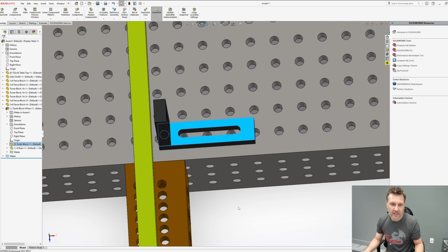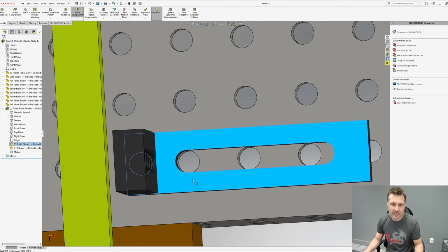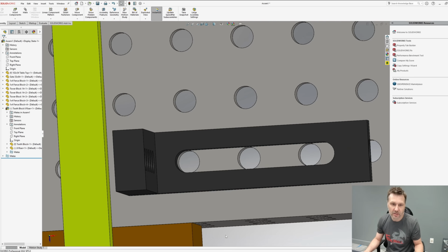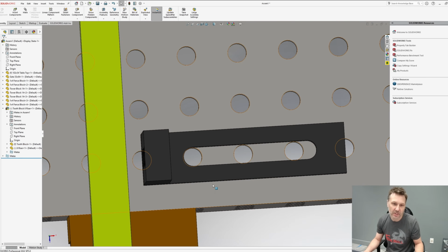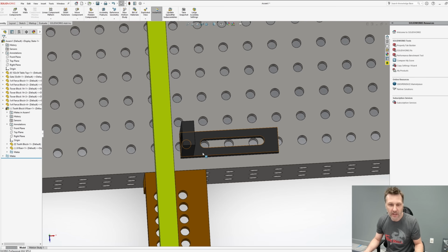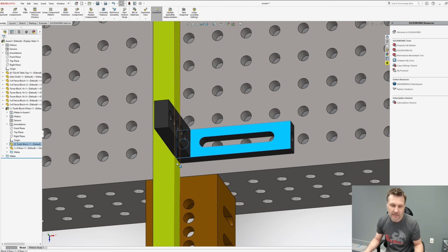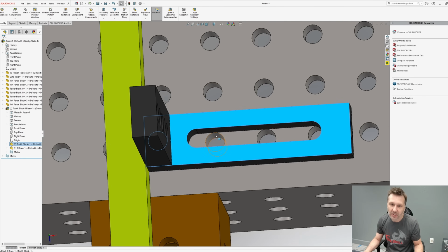So this is the way the tooth block works. Whatever the first hole is that matches up concentrically with the slot, this tooth block is technically in its 0, 0 position, which means it can't technically go back anymore unless you skip to this hole, right? So this would be 0, 0. What we're looking for when we generate a map of this is how far extended, which means how far forward does this block need to slide to give us our measurement or intersect our part, and how far did that move off the center line of this hole?